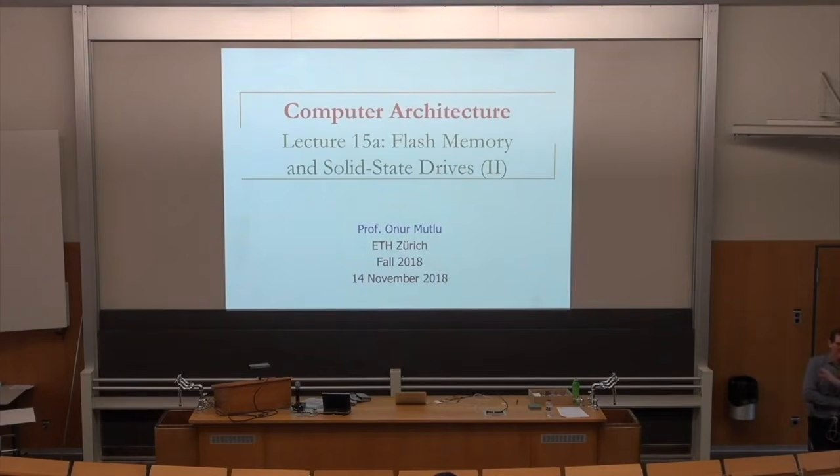It's very hard to tell without public information. But with the endurance problem, you have a layer of remapping potentially. It does move around with wear leveling. But the mechanisms differ. In Flash, for example, you have this mapping table, and DRAM is used as the mapping table. As I discussed last time, a logical address comes in, and it's translated to a physical Flash address.